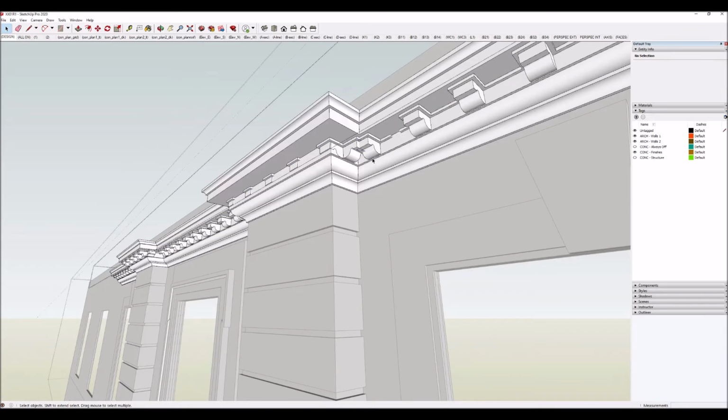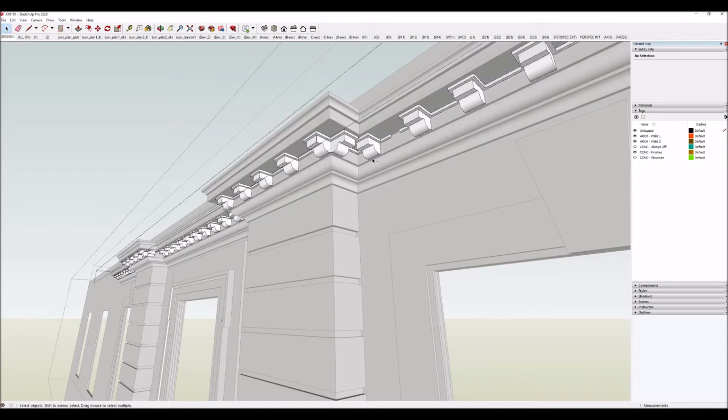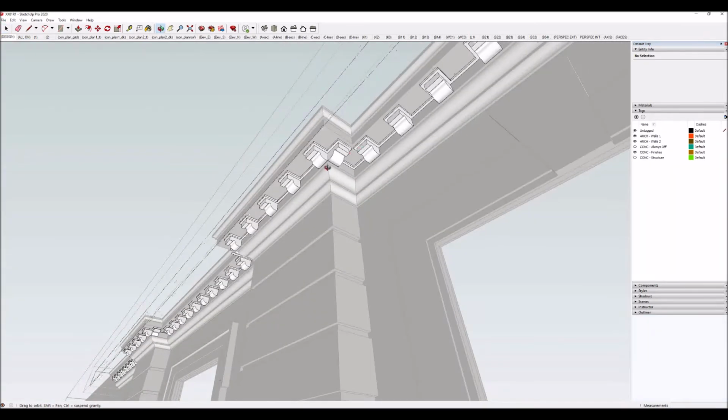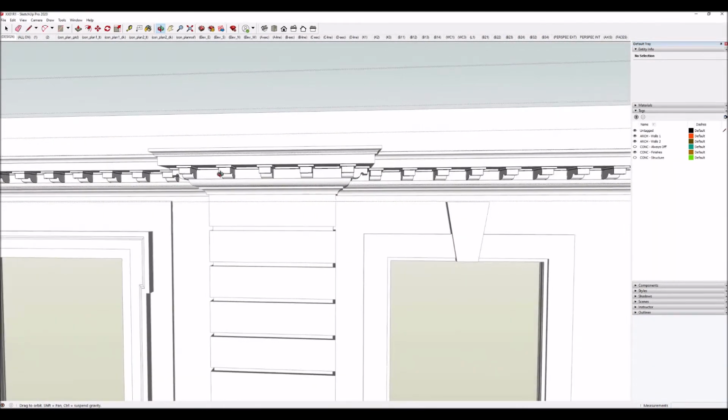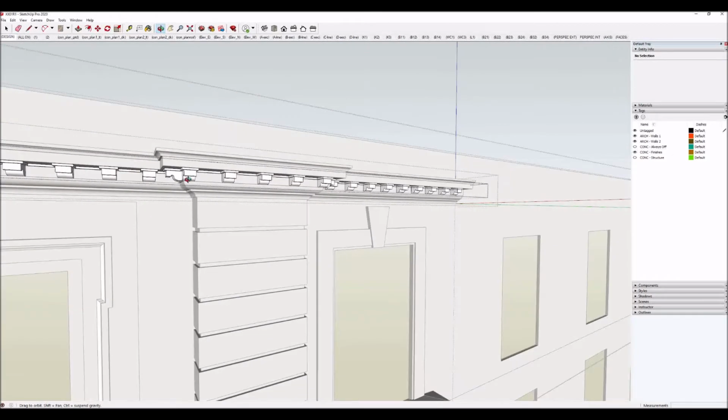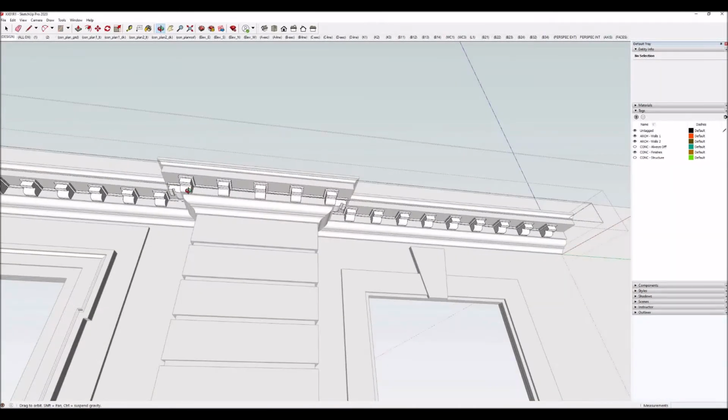So I had to do two things to solve that problem. The first was to pull all of these a couple of inches to the right, and then to extend the pilaster another 4 inches out. So I think it's now 8 inches deep. I determined how much to extend it because I knew the width. I laid out my brackets up here; there were 5 brackets in the drawing and in the photo, and the bracket came right to the edge.